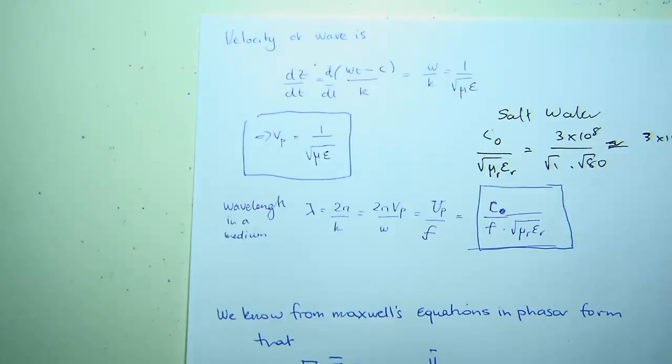Guess what? I will use a higher dielectric material. Maybe I'll use a ceramic. And if the ceramic has a relative permittivity of 10 or 12, all of a sudden it makes everything even smaller. That's why you need to know, because it affects all the analog components that you build on PCB boards. That's why I'm telling you about all of this, right?